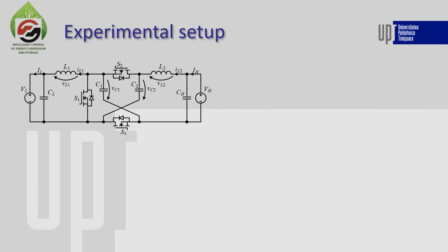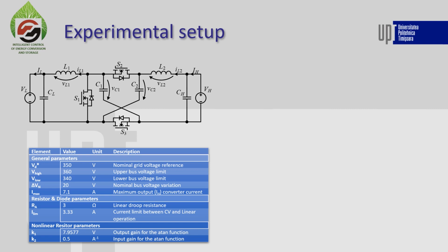The first hybrid switched capacitor converter is used for testing the droop methods, as it has inductors on each output, and the currents are already available for measurements because they are state variables and are considered for control purposes from the initial design. The parameters for testing the two methods are enumerated in the table for both nonlinear droop methods. These parameters are used in the static gain characteristics and in the control loop implementations.